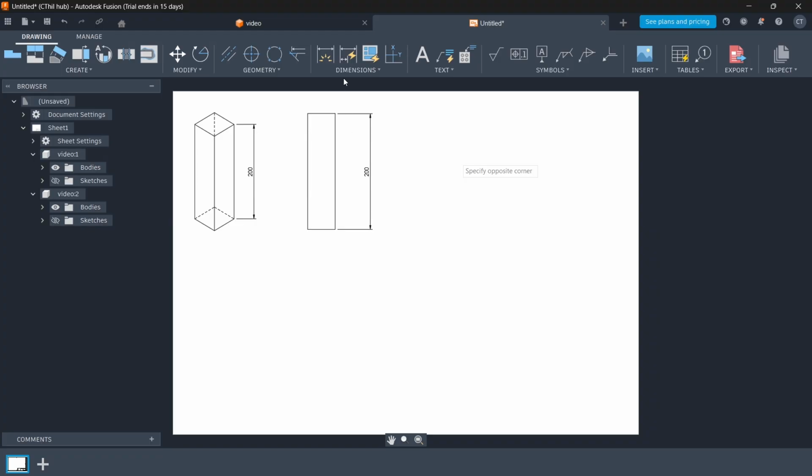And I would also recommend for the 3D view, you can use dimensions, but instead of using the normal linear dimension, which is the first one in that drop down menu, use the aligned dimension, and that's because the linear dimension is only really suitable for lines that run up and down. It's not suitable for lines that are diagonal. As you can see that line there, if I decided to use the linear dimension, keep in mind it would have shown up kind of weird, right?